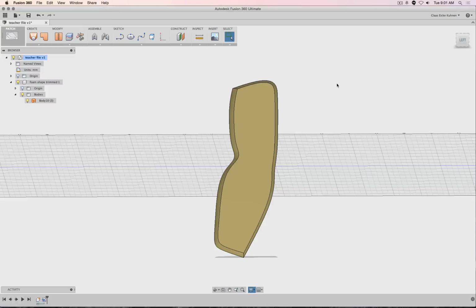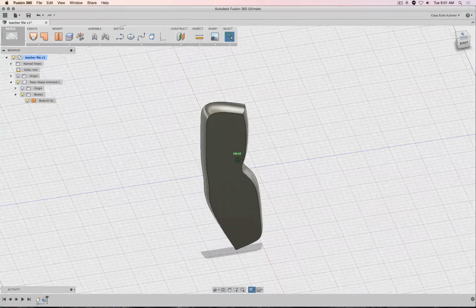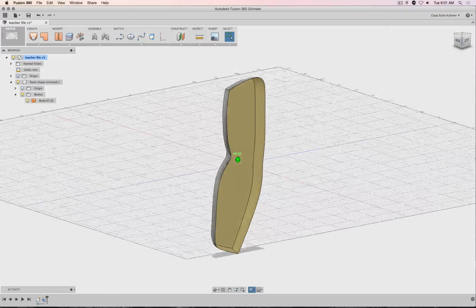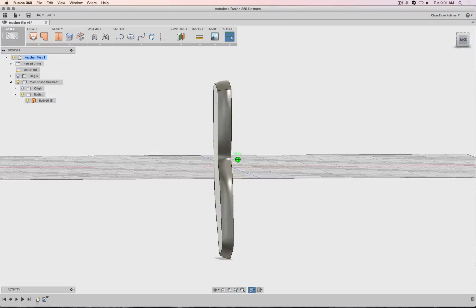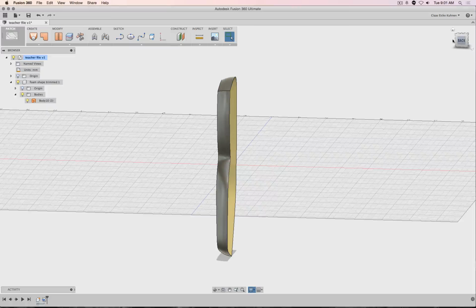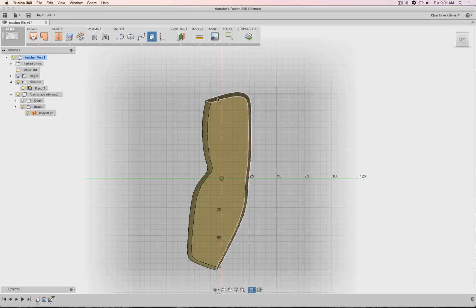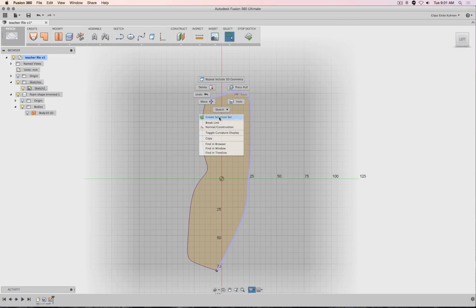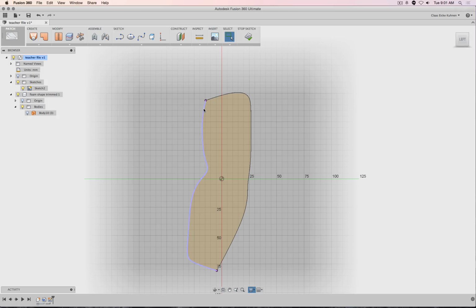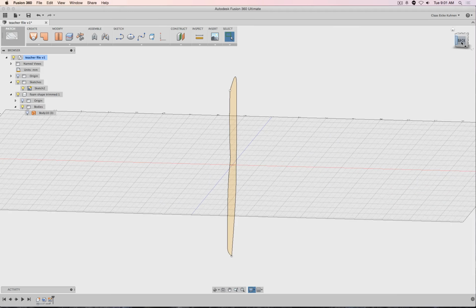Okay, so what I can do now is simply first, I would like to create myself the sketches for this model. So I'm going to create a sketch on the sketch plane, and then I go to 3D include those two lines, escape, and then there you see those lines, and actually I click them and say break link, so I do not make them interactively driven by the geometry, but really bake them into the sketch. Perfect.